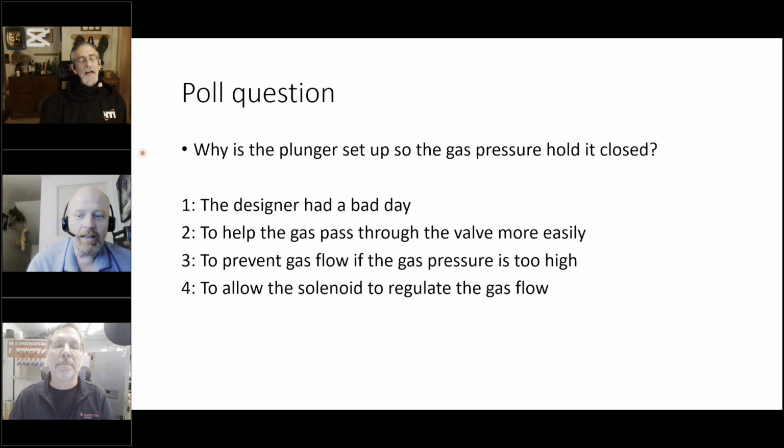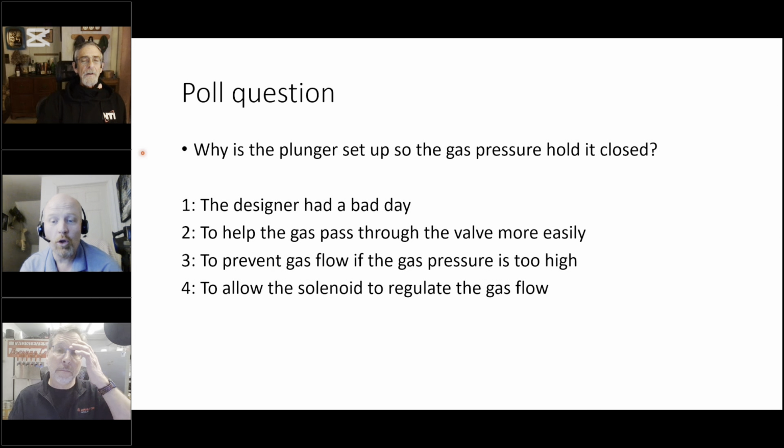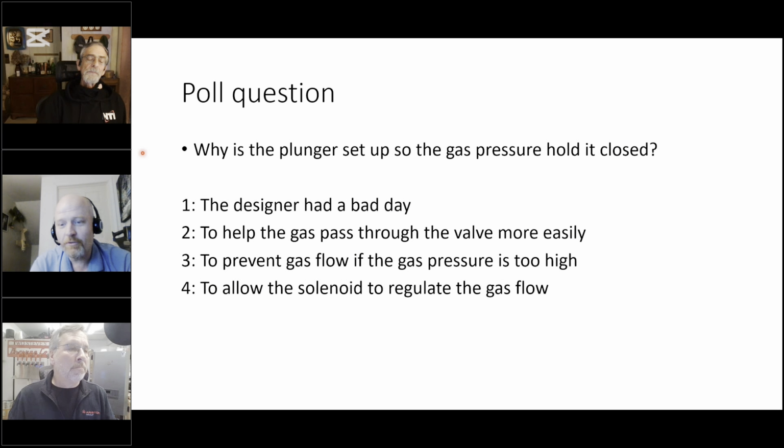Do you have an idea what that threshold is, Dave? The threshold at which the solenoid valve will no longer open. I know it's higher than 48 inches because I've actually seen pressure in our building when one of our regulators broke where we had 48 inches on the valve and it opened just fine. So it's a fairly high threshold. Very high, yeah. So the valves will open under a tremendous amount of pressure, but obviously if you put a huge strain on it, it doesn't do anything.